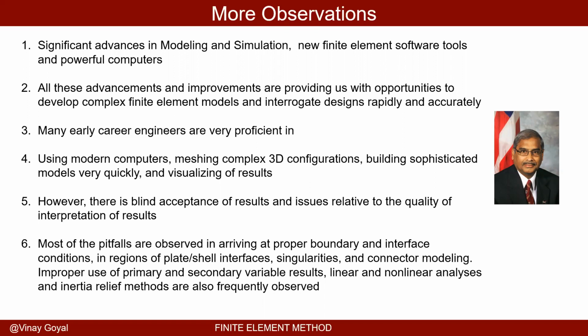Most of the pitfalls are observed in arriving at proper boundary conditions and interface conditions in the regions of plate shell interfaces, singularities, and the connector modeling, which is all of these interface modeling, regions of plate shell interfaces, where there are stress singularities, and connector modeling. These are the issues where you need to pay special attention. That's where all the problems are.